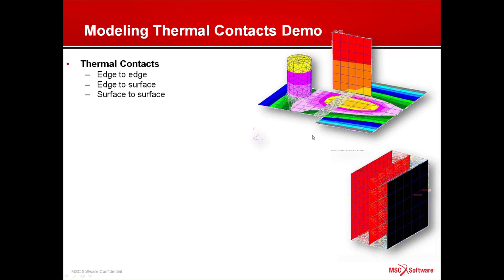And just a little bit about that math, although it's more difficult than I understand, actually, how we do that. One of our developers spent quite a bit of time coming up with the algorithms. But the way you can visualize it is, below that disk that's connected to this big plate, it's as if we would put a material in between and do a tetrahedron mesh on that, just mesh that material and allow heat transfer to only flow perpendicular to the joint. By doing that, we eliminate some potential errors.